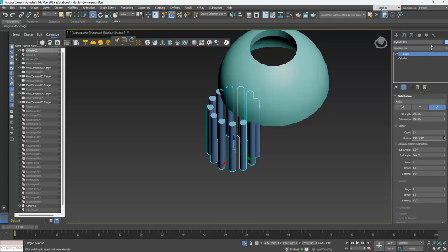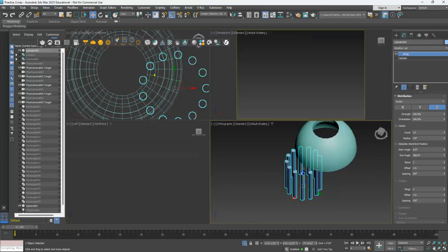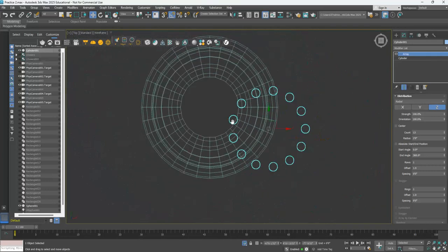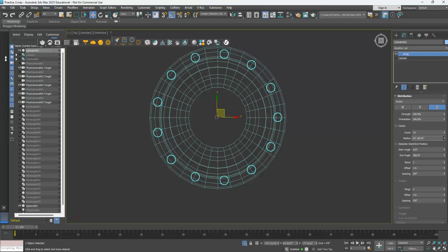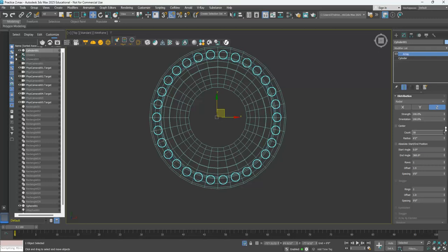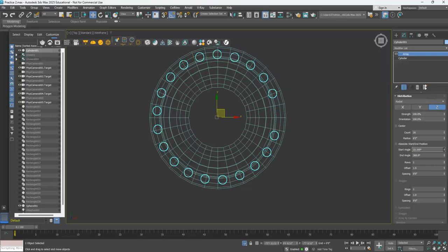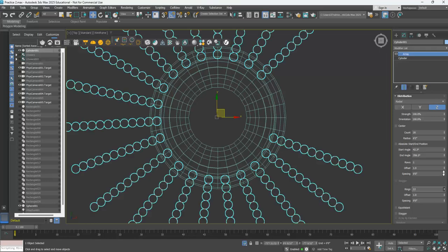So we can create here, for this shape that I have, the main thing is I need to locate my column right in the middle. For now I'm just going to guess, somewhere there. Then I can play with the radius to get it pretty much out to the edge. Then I can play with how many columns I want, or less. The spacing, we can do the angle here. So we can say, are they going to array 360 or a bit less? And we can make like an entrance. Here, 360. And then we can do it like this.